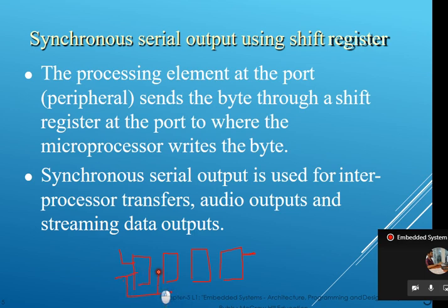And there are two types, synchronous and asynchronous shift registers. Here I am doing the synchronous, which works on a common clock pulse. In asynchronous, the output of the register is given as the clock for the next bit. Okay, this is the synchronous one. So every flip-flop is connected to the single clock. Here data will be there, and it is connected to here. So I am using the D flip-flop, and this is your data output, and this is your input.